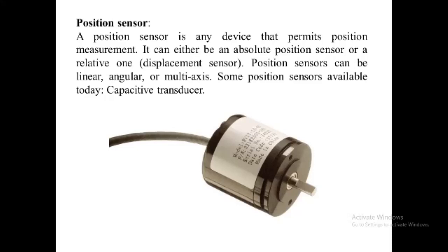One main disadvantage of the incremental encoder when used as a position sensor is that it requires an external counter to determine the absolute angle of the shaft within the given rotation. If the power is momentarily shut off or if the encoder misses a pulse due to noise or a dirty disk, the resulting angular information will produce an error. One way of overcoming this disadvantage is to use an absolute position encoder.